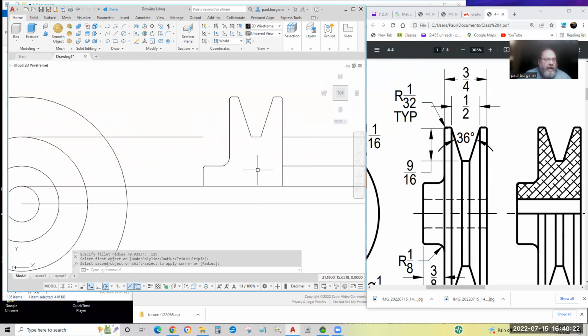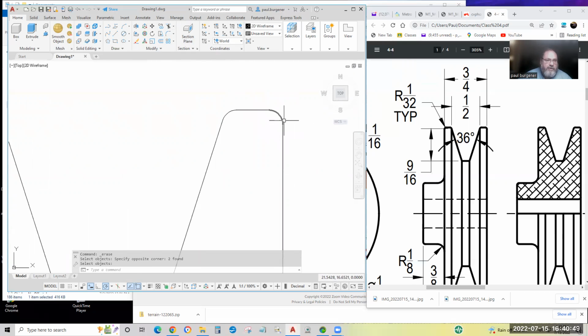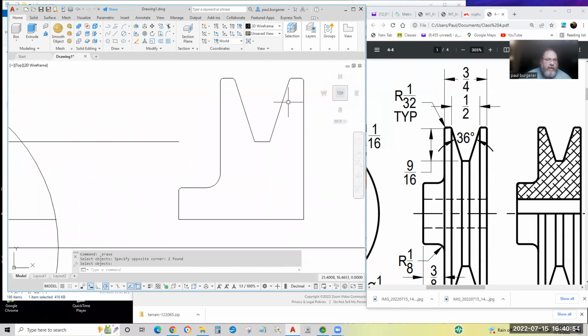Now, the elegant, proper, impressive way is to trim and shave off this and weld all these lines and arcs into a closed polyline with the join command. By the way, we can lose these 2 guidelines before you ask what they're still around for. An easier way, just in case you got double lines somewhere or 0 point lines at the ends of lines or radii, an easier way is the crosshatch boundary.